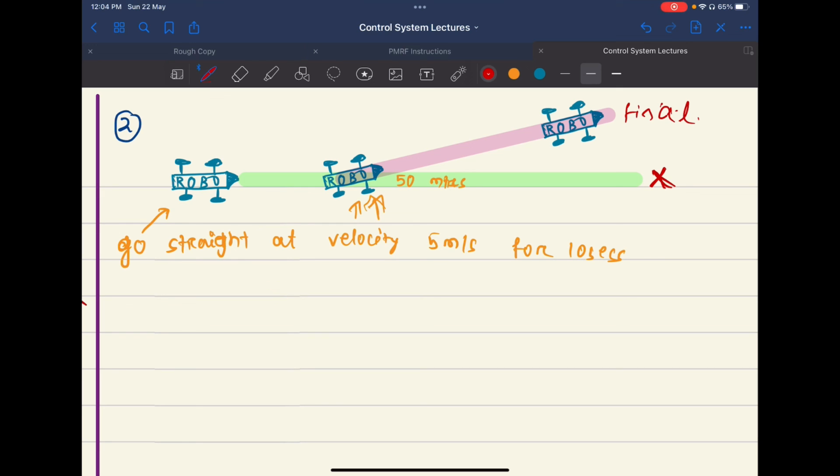So that means E is equal to Y divided by D times G. So I can also write V minus Y times H equals Y by D times G. Manipulating this, I can get Y by V equal to DG by 1 plus DG.